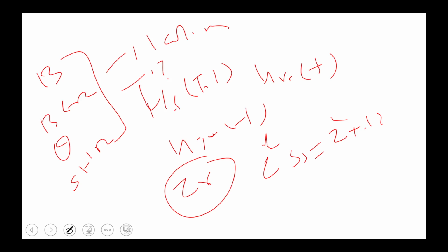Then you have to consider the total number of amplifiers we have to take through the link design. It will be 3, 4, 5, after 20 kilometers you have to put one, or after 60 kilometers you put one. So we consider that loss also. Then you have to decide that this is our loss. Then this is our rise time budget for our signal.